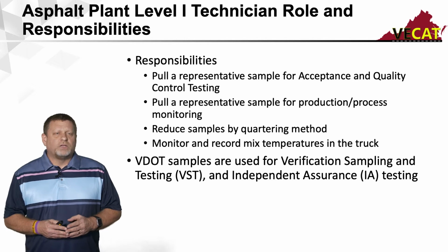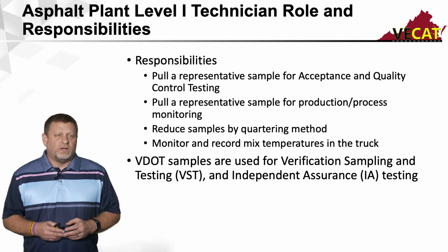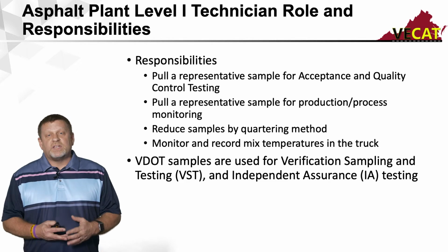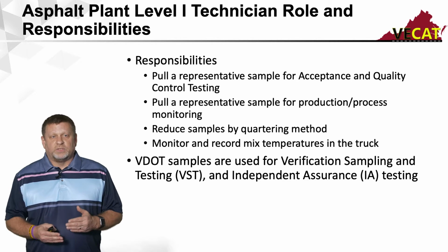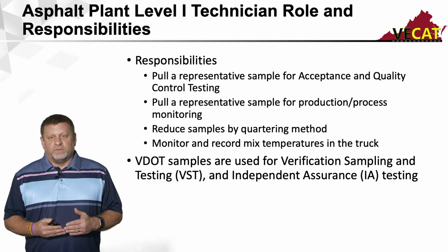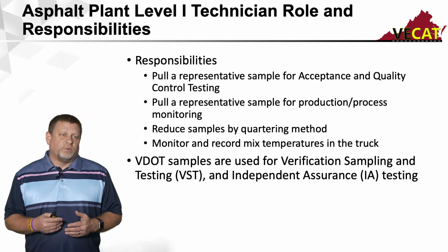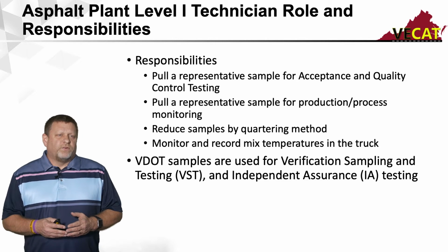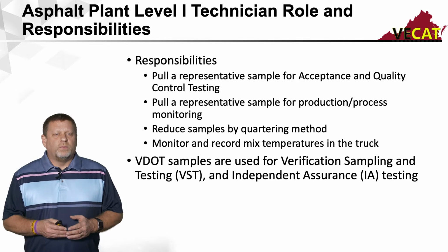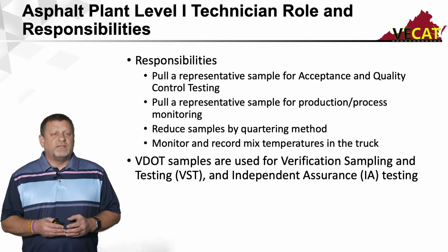And then he's going to monitor and record mix temperatures of each truck. Every time we take a sample, it's important we take a temperature. There is a place on all the forms for the temperature of the load when the sample was taken. For the VDOT side, we're going to be working with some verification, sampling, and testing, and the independent assurance samples.